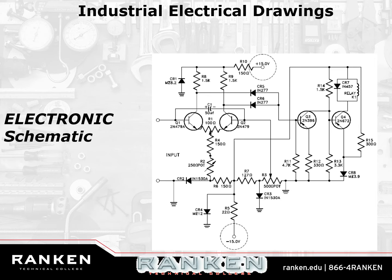Like I said, chances are you'll never have to troubleshoot something down to the component level. Almost never. You're going to figure out which board it is, and you're going to throw it away. Especially in PLCs, an I/O board is going to go out. Something's wrong with the PLC. You're going to go out there, open the door, and one of the I/O boards is not going to have any lights on. All the other I/O boards are going to be blinking at you. Blink, blink, blink. There's going to be one I/O board that's just completely black.